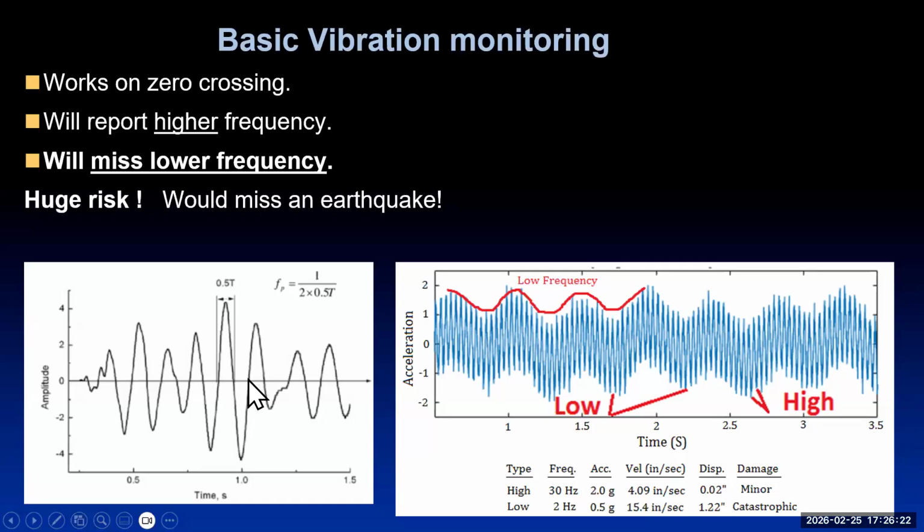But here's the problem. And RI 8507 talks about it quite well in that it's a broadband response. You have energy at all these different frequencies. Just because this mass responded that way, it was impacted by a number of different frequencies, which comes out in the variability of the amplitude. So when you do a spectrum on this, you actually get all these different frequency components.